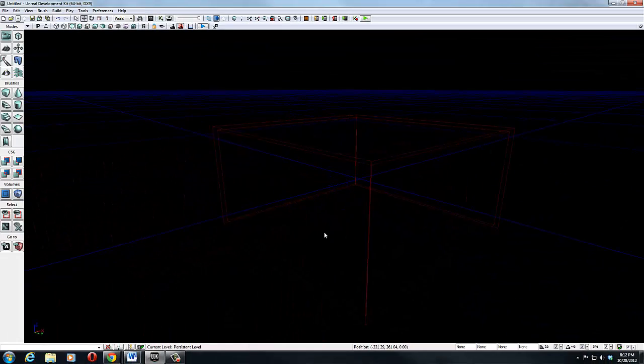Well, you'll notice when you turn on hollow, you actually have a setting for wall thickness. This wall thickness is what gives you basically the thickness of your walls. And once again, you'll notice that that number is divisible by 2. It's 16. The other thing you need to know is I'm going to come in here and say build, I can close this panel down, and you'll see it built this builder brush.